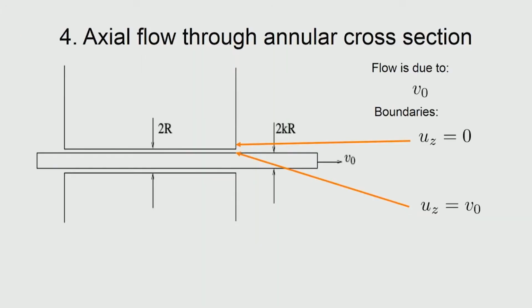So, we now move to the axial flow, but with a small deviation. We earlier had a pipe with the circular cross section, but in this situation we want to have an annular cross section. So, we have our domain a little different. So, the domain is looking like an annulus. So, the domain is defined in this manner. So, if you have kR as the inner radius, so this is the domain, okay, and the liquid is actually going in the annular region like this and in the axial direction.